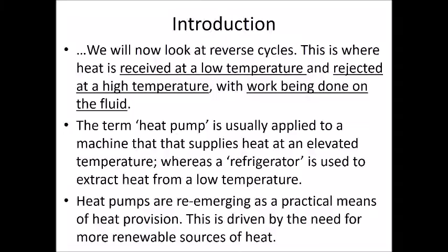So we're doing reverse cycles, aren't we? So we take heat from a low temperature reservoir and we reject it at a high temperature reservoir, and work is being done on the fluid, not the other way around, not the fluid doing work on some of our mechanical drives. Our mechanical drives are doing work on the fluid, which is what you saw with that video where the pump is doing work on the refrigerant in that case.